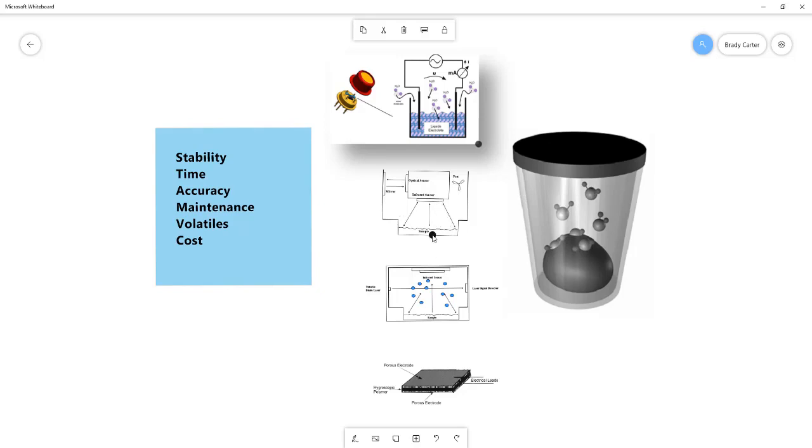The dew point sensor measures the vapor pressure inside of the chamber by the dew point temperature, and then the saturated vapor pressure based on the sample temperature, and the two together give the relative humidity or water activity. And a tunable diode laser has a laser tuned to a wavelength that's specific to water, which can then measure vapor density inside the chamber, which then relates to vapor pressure, and also measures the sample temperature to get the saturated vapor pressure.